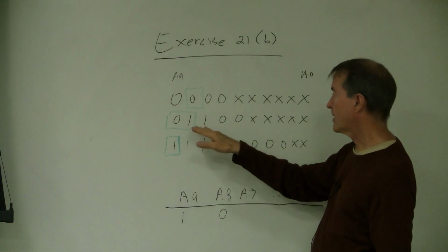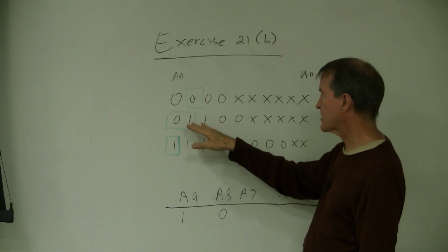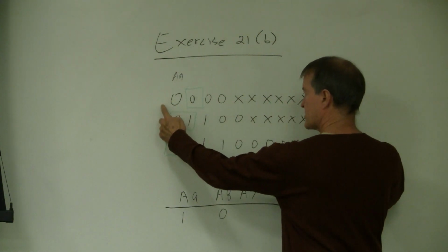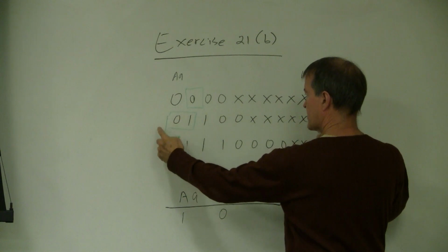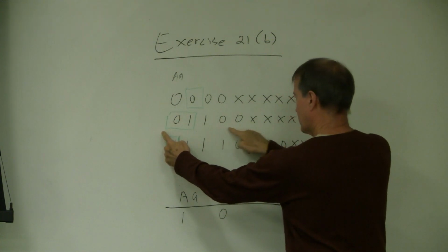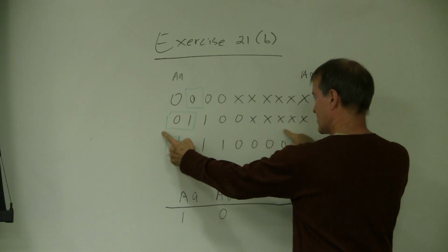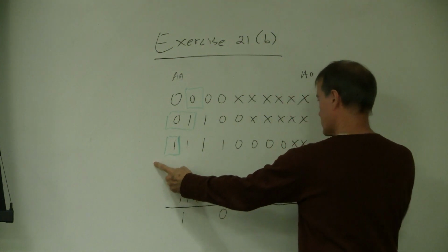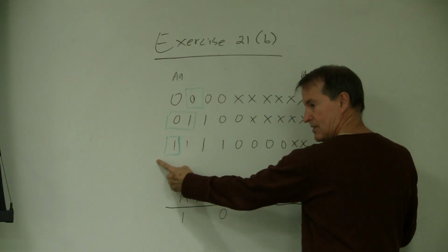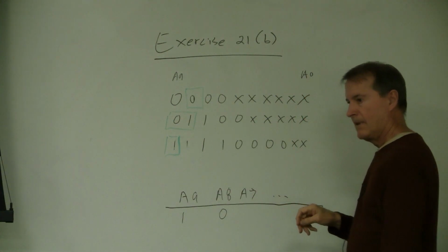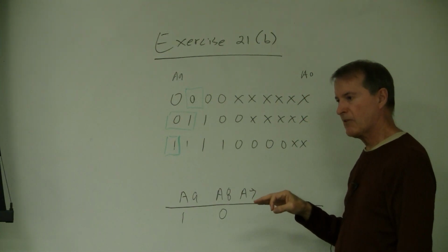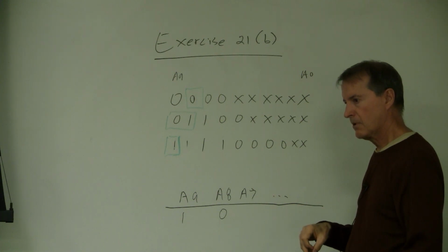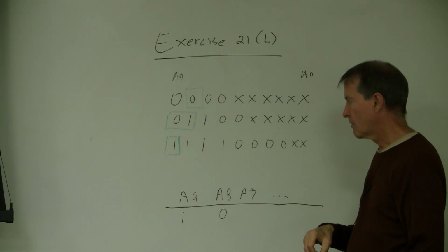What we want is a memory map where this one is mapped at address 0, this is mapped at address whatever this 0000 is, and this is mapped at this address 110000. And we don't want there ever to be a conflict of having them both on the bus at the same time. Right, I get that, but it's not an X, it's a 0, so.